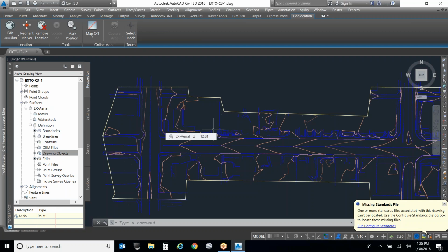All of that is in that information. In addition to that, if they collected it with a theodolite, there's going to be a level run, and the level run is in there, and it's just a copy of their book, basically, giving you the notes that they write, and giving you the accuracy that they came up with out in the field.